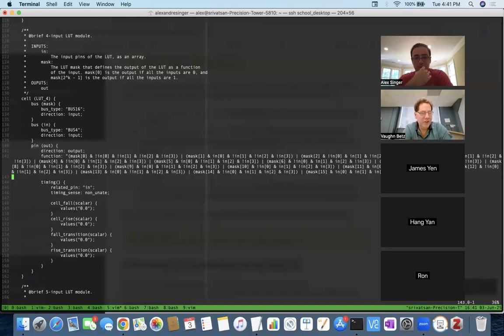Let's look at this interesting additional thing: the mask, the LUT mask, which is not really an input. It's marked as an input here, but it's constant. It won't actually change. So it's kind of interesting whether the timing analyzer would figure that out if you didn't give it. You didn't put any dependency edges on it, so it's fine. Exactly, there are no timing arcs. I noticed that. So it's treated almost like a signal that came in, but it's a solid state signal. It's either 0, 0, 0, 1, 0, 0, 0, and for time immemorial it's always been those values, which you can think of as if the FPGA was just programmed.